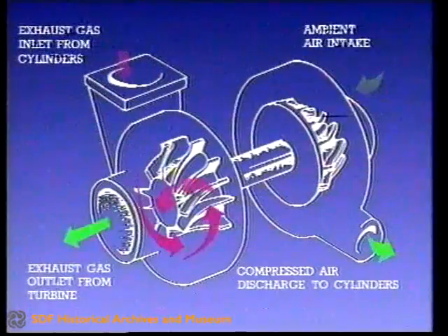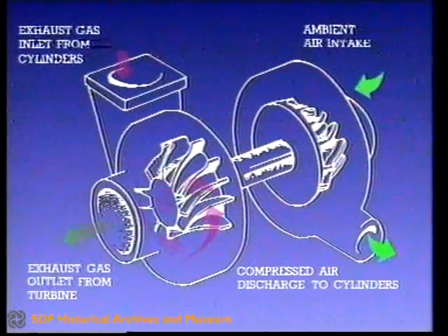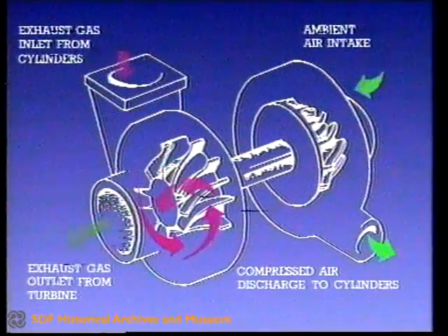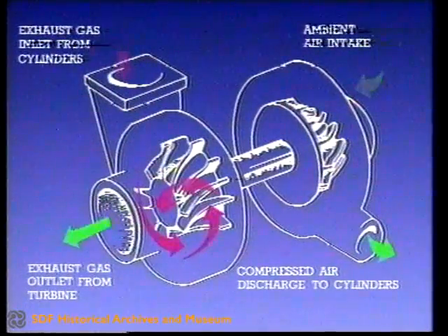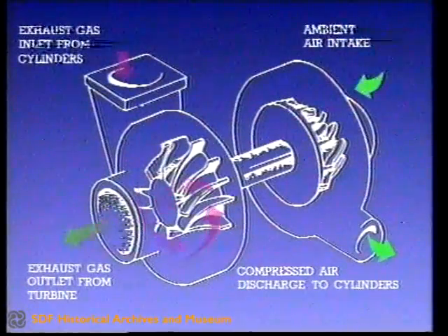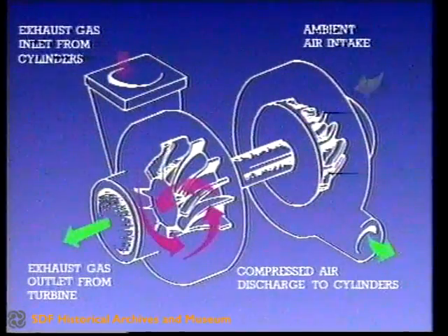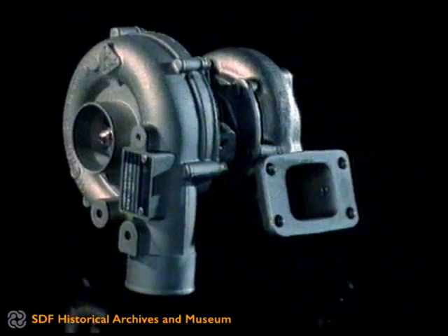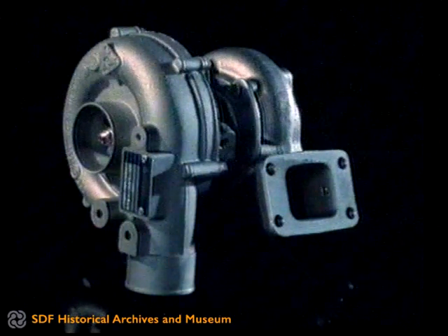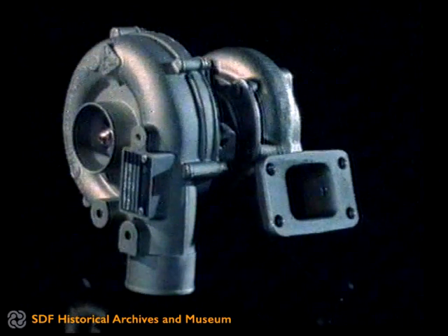How does turbocharging work? By means of a centrifugal compressor, which compresses the air in the induction pipe before introducing it into the cylinders. The compressor is nowadays, in the majority of cases, activated by a fan driven by the exhaust gases. Turbo compressor, a solution which offers the advantage of not taking any power from the engine, but of recycling the energy contained in the exhaust gases, which otherwise would not be used.